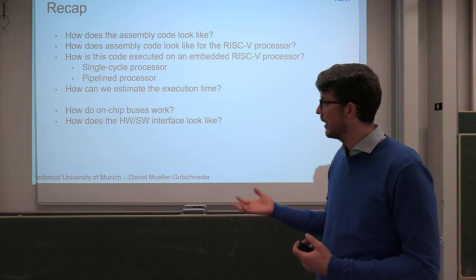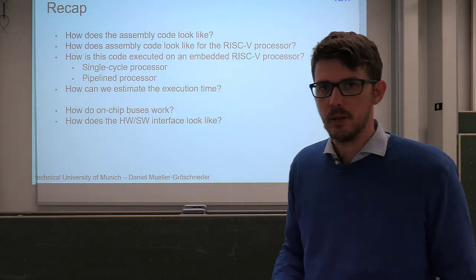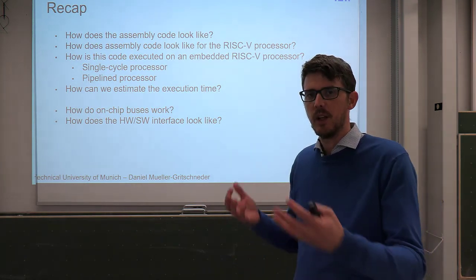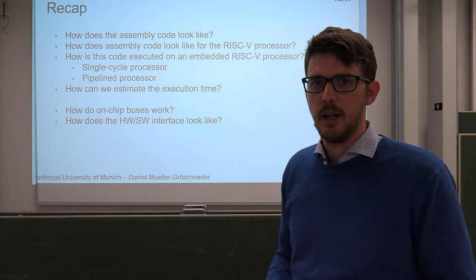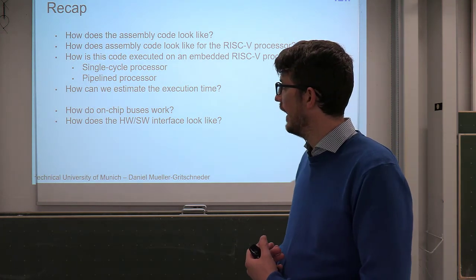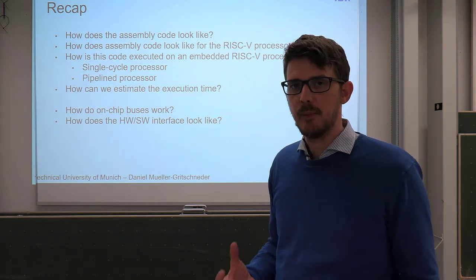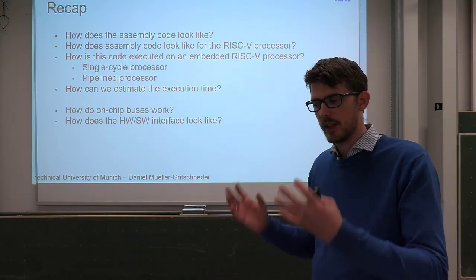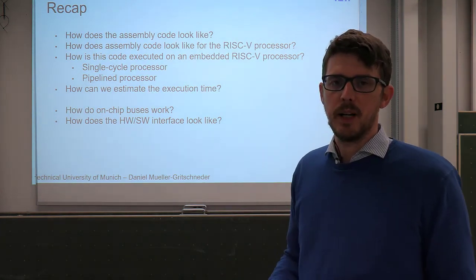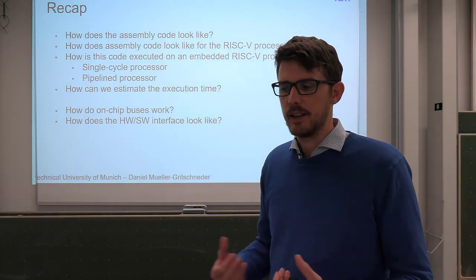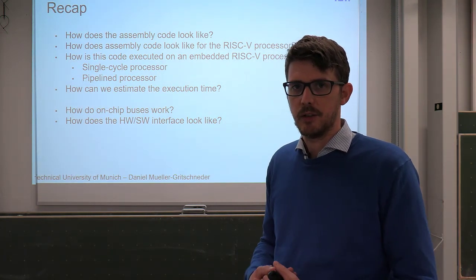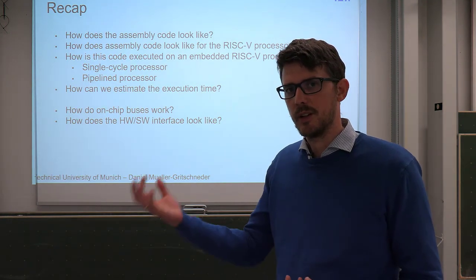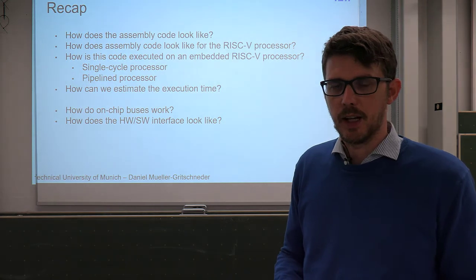For that, we looked first at how an on-chip bus looks like, so how you can interconnect your processor to the memories, to IOs and so on. And then we took one example with this hardware accelerator, where we said, how can we take this hardware module, map it to the bus, write the software, and then this hardware accelerator is usable by the software, such that some of the task is running on a processor and some of this task is running on the hardware accelerator.